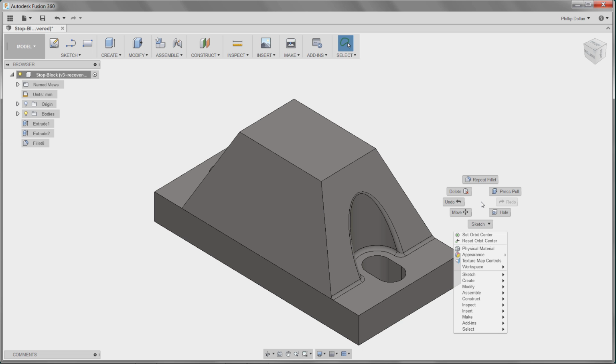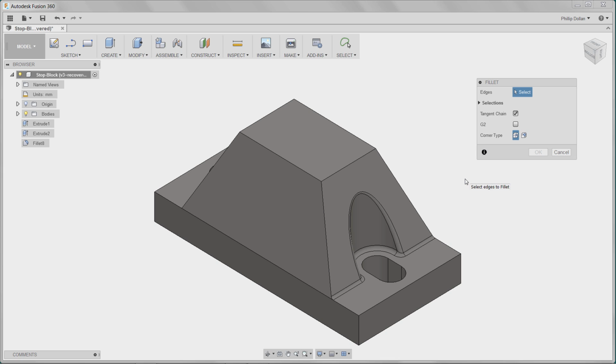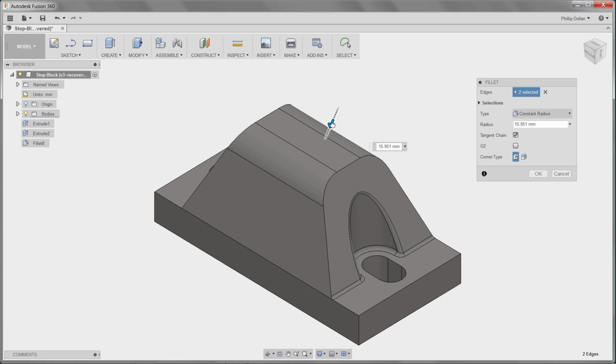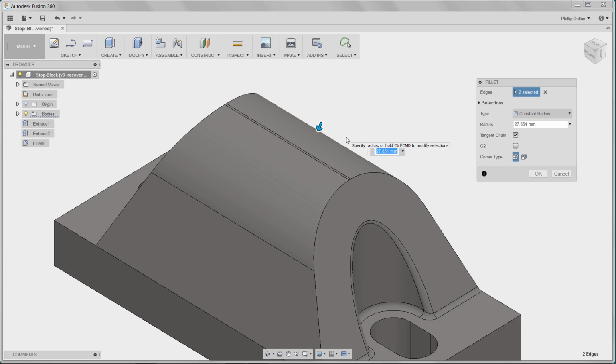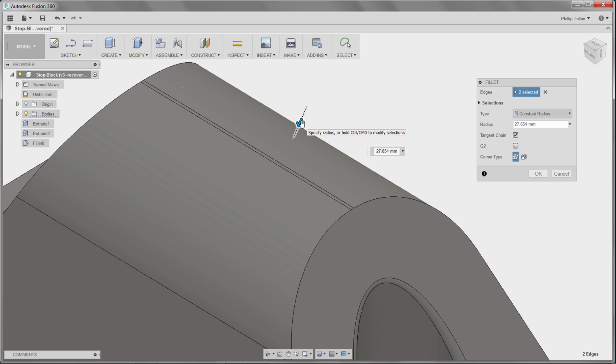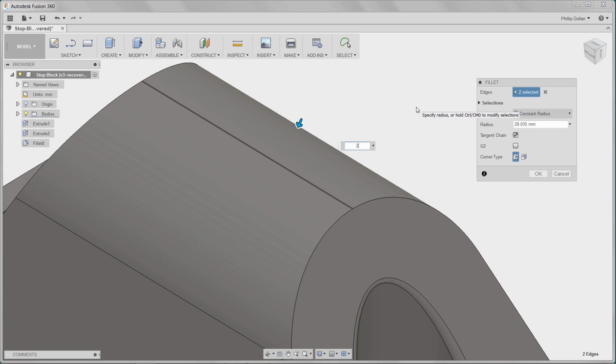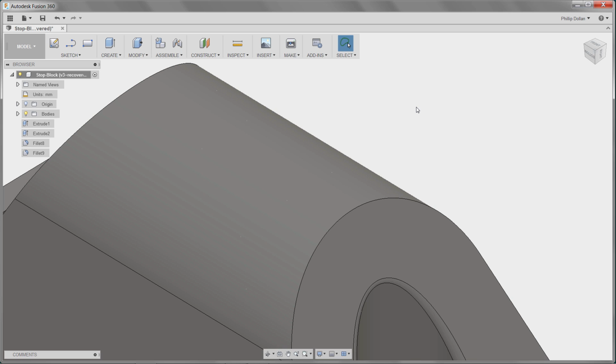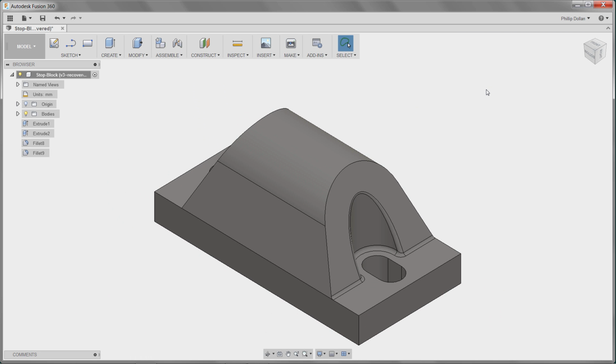Back to Repeat Fillet. I want to create a rounded feature on the top of the part. I could create a sketch, but fillet works in this case as well. So I'm going to drag it in. I'm looking for kind of a minimum solution. I want to leave the maximum amount of material on the top of the part. So just dragging that down. Now it looks as if about 28.25 would be a good solution. You can see those edges have disappeared. So 28.25 was the best answer.